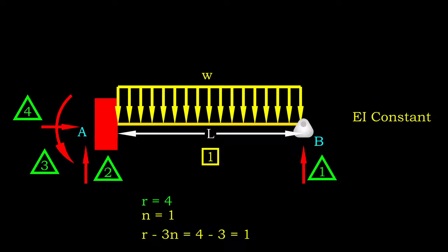To solve for a statically indeterminate beam, we may use force method. In this example, we have a prop cantilever with 1 degree of indeterminacy. The beam section is prismatic and the entire beam is homogeneous. In this case, usual equilibrium equations do not solve for all unknown reactions.